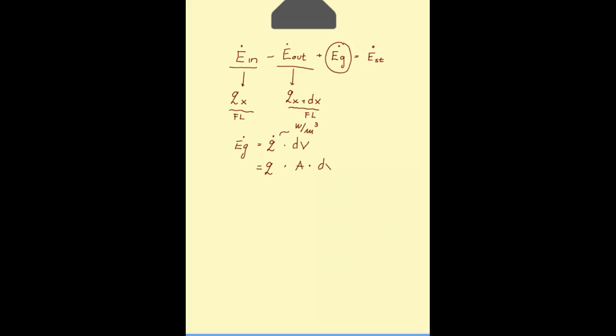After considering all three components of the energy balance, we are now left with a term that expresses the changes in the amount of the stored thermal energy. Note that this change of the thermal energy is only due to the changes of sensible energy, which is the energy related to changes in temperature. The latent energy, due to the change of phase, is not considered.